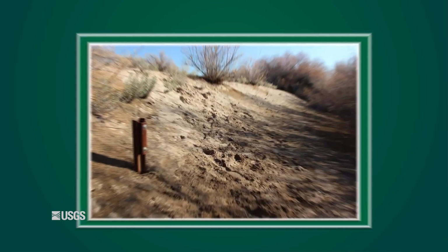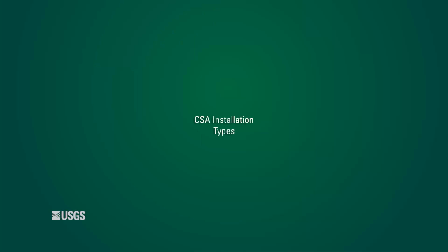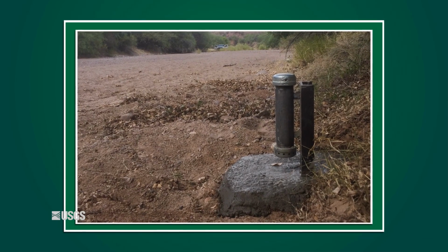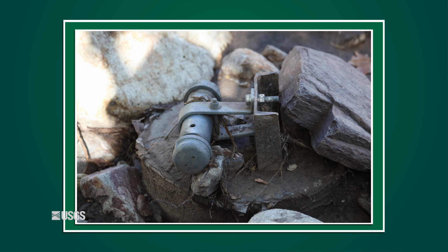The design of the installation will vary depending on channel composition and anticipated flow intensity. All installations are designed for low disturbance and survivability. This limits debris pileup and drawdown that can reduce the accuracy of the sensor readings. Here we have several examples of installations. One in a sand channel, a bedrock installation, and another in a cobble channel.